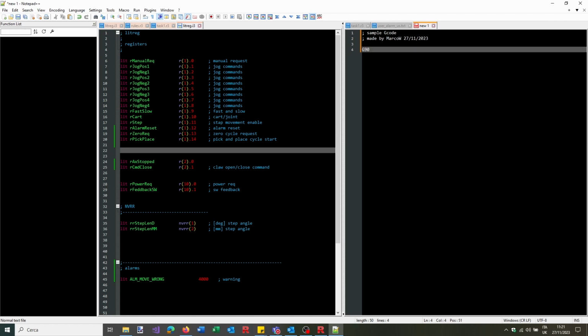And now let's say G90, which is the absolute coordinates. Now I'm not explaining so much about the G-code. If you would like to know more, I can make another video for this. Now let's just say we use G90, then we say F, which is the feed, let's say 20,000, this is the feed, so it's millimeters per minute. Let's say that 18,000 is easier to understand because it is 300 millimeters per second.